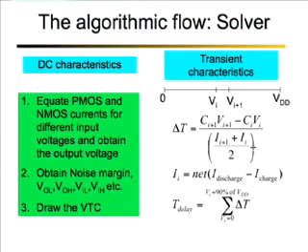So instead of doing the simulation in the time domain, we resorted to doing it in the voltage domain. By that is meant that we divide the voltage grid from 0 to VDD into n different number of points. Whenever we have an RC circuit with the capacitor being discharged or charged through a resistive circuit, for example a PMOS charging the output load or an NMOS discharging the output load, we can evaluate the time delta t as the difference of charge between these two voltage points divided by the average of the current that flows in this voltage range.